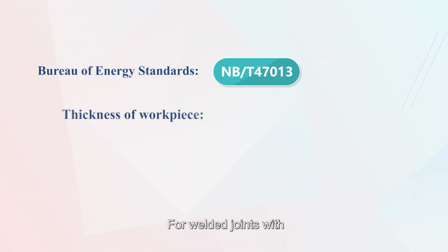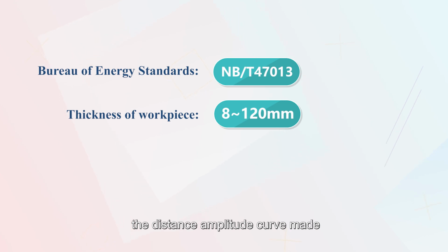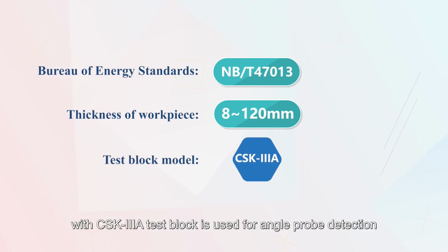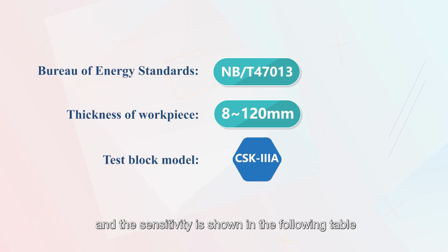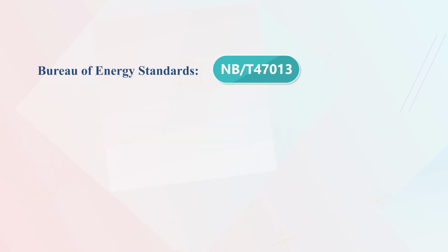2. For welded joints with a workpiece thickness of 8 to 120 mm, the distance amplitude curve made with the CSK-IIA test block is used for angle probe detection, and the sensitivity is shown in the following table. 3.